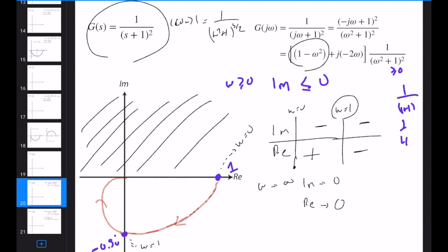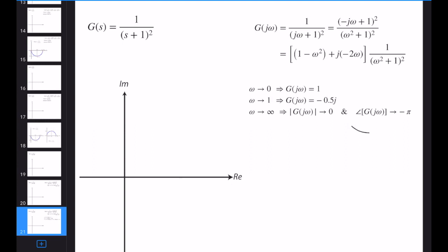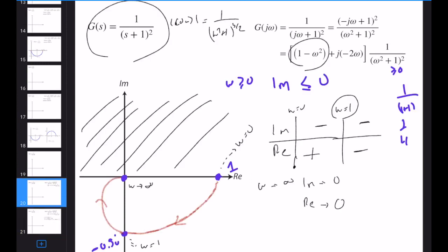Indeed, we can also compute the angle of arrival, by computing the phase angle when omega is going to infinity. If you look at the behavior, we can fairly easily see that this will be approximately equal to 1, and this will be going to 0, so technically the real part will dominate the behavior and it will be minus pi. But it's really not important, it's important just to have this kind of behavior. And this is my polar plot.